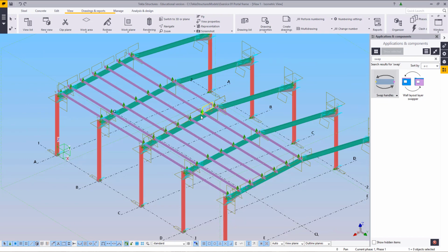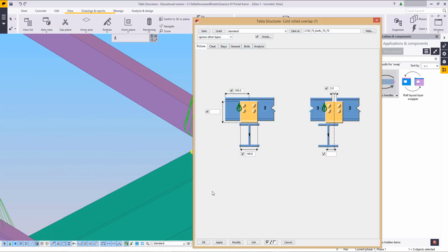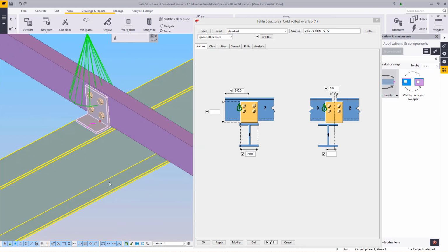Now, after doing the purlins, I'm going to put in some knee stays. Basically a knee stay is just a piece of angle line that will go from the bottom of the rafter up to the purlin.